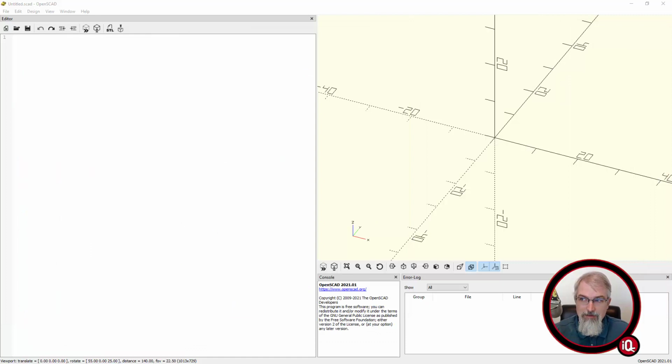I'll explain what I did. So first of all, we'll copy that in, just some notes that I made, and also the detail. I usually just set it to 200, and that sets how much detail there is. The smaller that number is, the more blocky it looks. It'll render quicker, but not look as good. So if you have a problem with your system, you could bring that down to like 10 or 15 or 20. It'll render faster, and then bring it up to a higher number when you actually want to make the file.